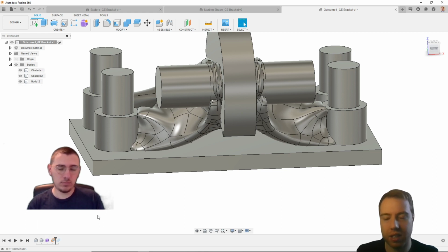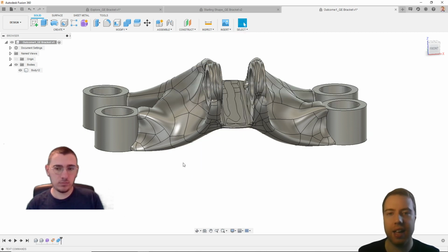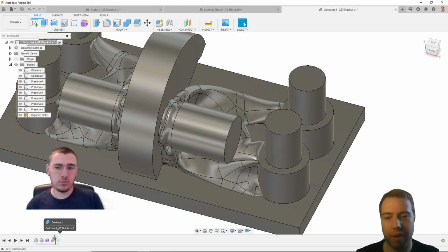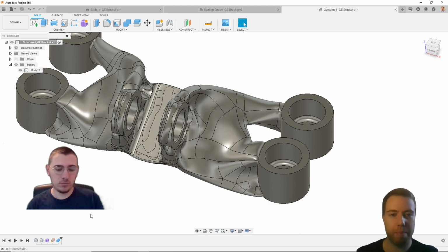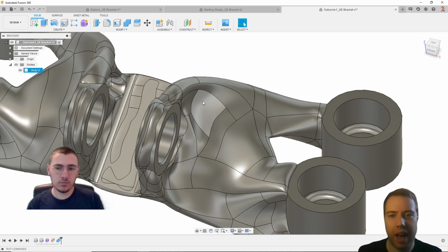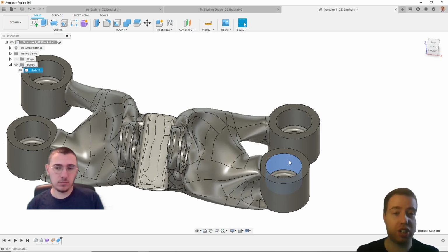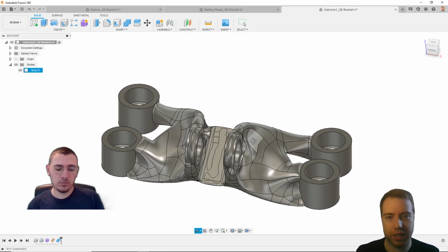So if I keep dragging this along a bit more, you'll see what we need to make sure is that this final design accurately contains our preserved geometry and our obstacle regions, and it doesn't interfere with those. So we do a couple of Boolean operations to make sure that we Boolean add our preserved regions and subtract our obstacle regions. And all this does is clean up our design, and it makes sure that we have nice clean surfaces and faces, which are just taken directly from our preserved faces and geometries.